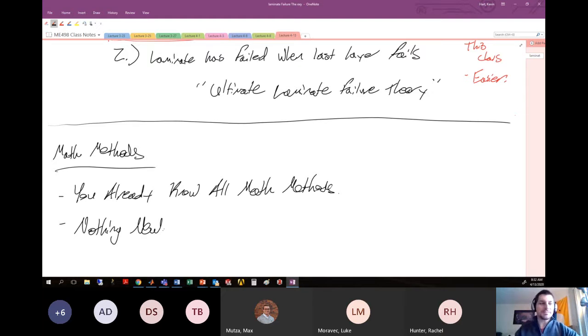If I think about, I'm going to make a laminate that has a certain stacking sequence made from a certain series of fibers and matrix material. I'm going to load it in this certain way. How can I predict how it's going to fail? There's a very long process there. You have to think about, what are the fiber properties? What are the lamina properties? How am I going to create my Q matrix? How much stress and strain is there going to be on this guy if I load it a certain way? Then how do I develop the stress and strain in the individual layers to bring in my failure theory? There's a lot there. Okay. So I only really need to teach you the process.